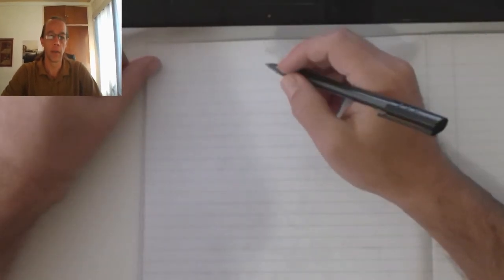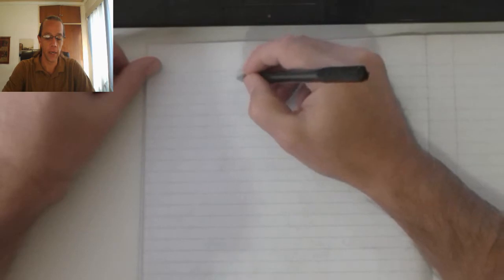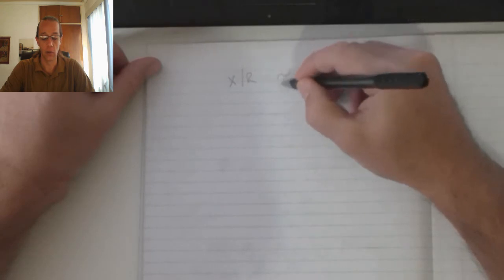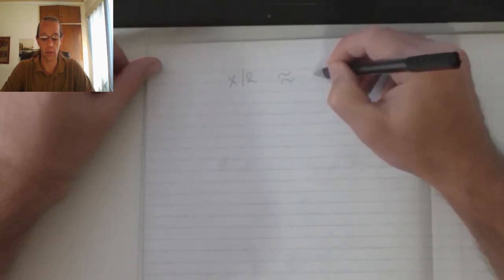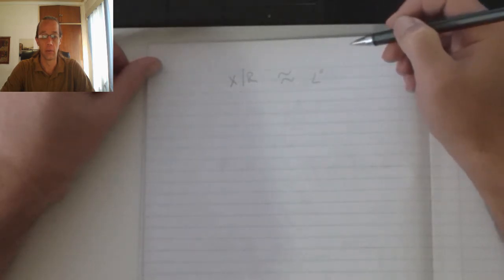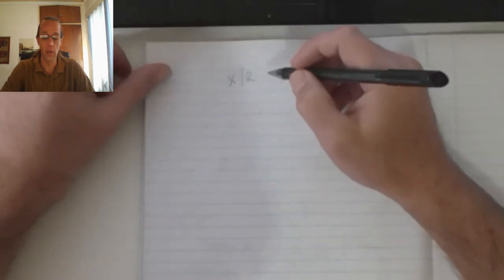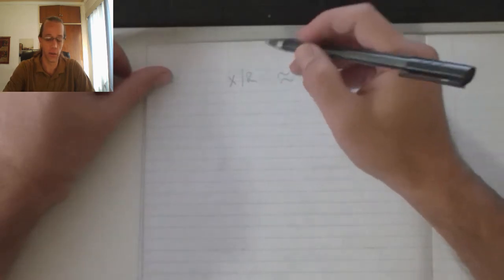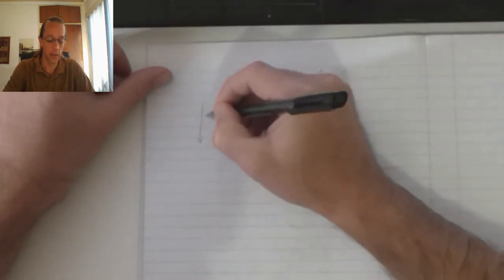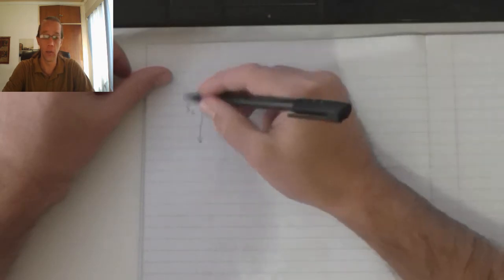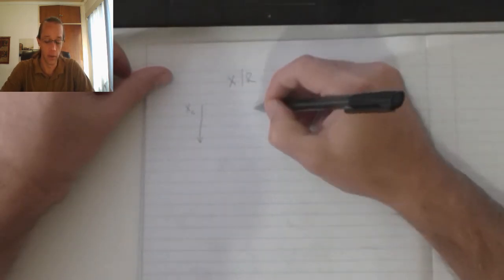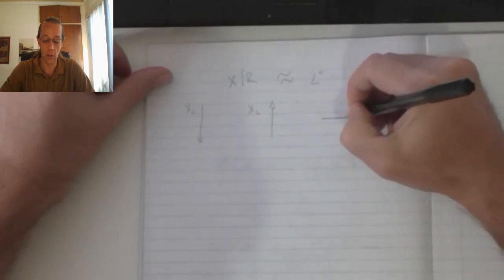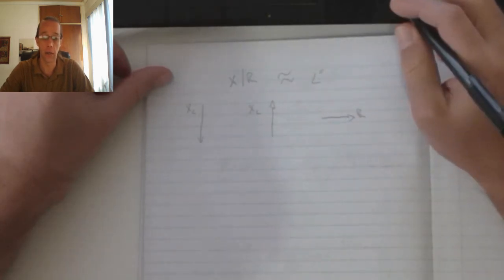It's important to remember that in RLC circuits, the reactance or the resistance will determine the phase angle. As a result, when we look at the effects of AC on an RLC circuit, we need to remember that the capacitor will cause a downward shift in the total, the inductor will cause an upward shift, and the resistor will cause no shift at 0 degrees.